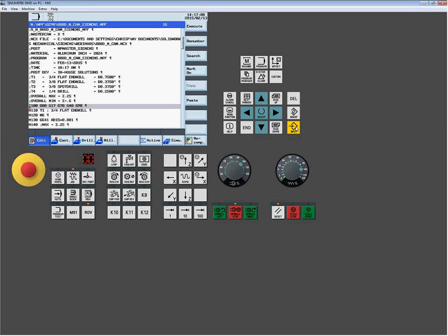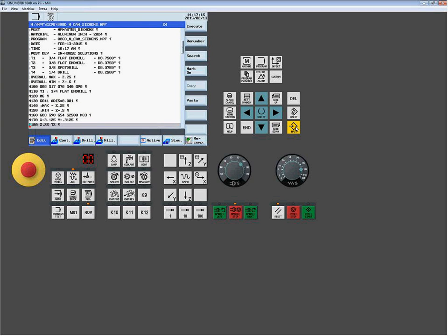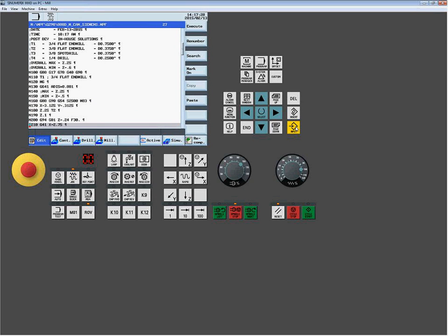Then I start to see the header protocol, my tools, my tool changes, technology statements, and we can start moving down from there. My spindle commands, different things being fired here. So first, when I'm methodizing or setting up a new part to start to simulate and then eventually run, I want to make sure that I have the appropriate tools created, set up for me in a tool table. I see T1 through T4.